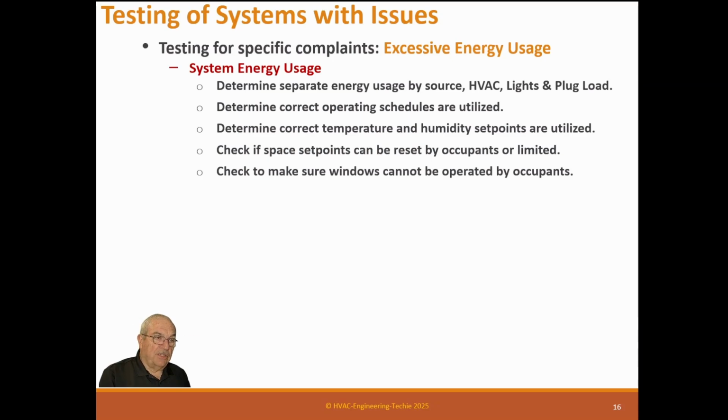That sounds strange, but if the occupants want fresh air, so they open their windows and they leave them open when they leave, now all of a sudden your building is open to the ambient and you can't control it. Verify temperature resets are working correctly.